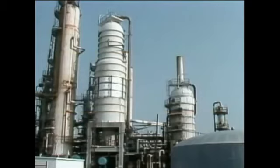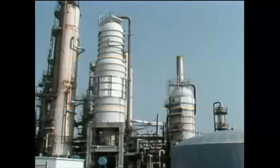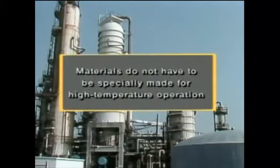A second reason for using vacuum distillation is that running a tower at high temperatures requires more energy or fuel. Operating a tower at lower pressures allows the distillation process to be accomplished at lower temperatures, which requires less energy. A third reason is that a tower that's designed to operate under vacuum, and therefore at a lower temperature, can be constructed of materials that do not have to be specially made for high temperature operation.